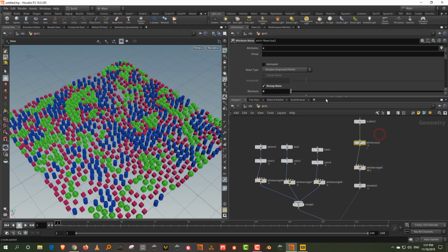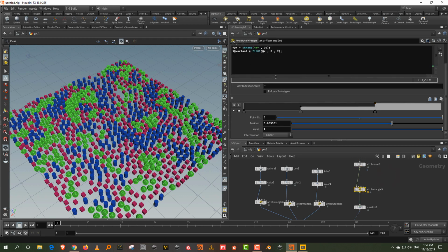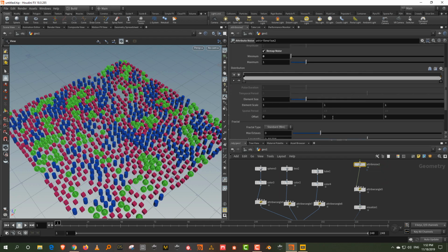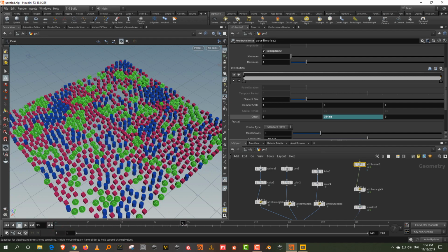So what we did was we generated a noise map called C, and then we used a ramp to adjust C into 3 equal sections, or 3 sections essentially. And then we used a variant with a fit range to reset it between whatever you want. If I bring this down here, as you adjust this, you can adjust that accordingly. And if I adjust the noise map, if I animate this, let's say with @Time, then you can very easily have these guys adjust.